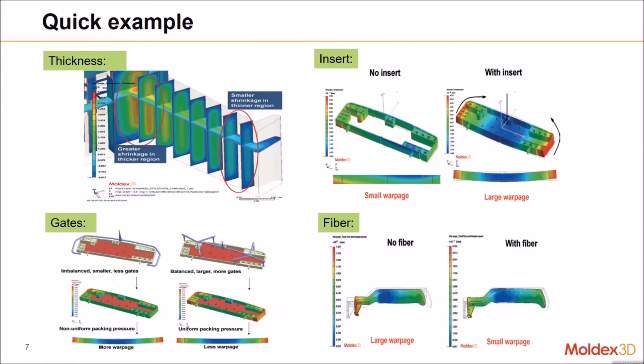So the amount of shrinkage can be reduced by enlarging our gate size and also adding more gates to create equal length of each runner. Thereby the warpage condition is improved. So you need to think in more detail about your part design to make sure each length from the sprue to the gate to your part is the same. It is the better way to prevent the warpage problem.